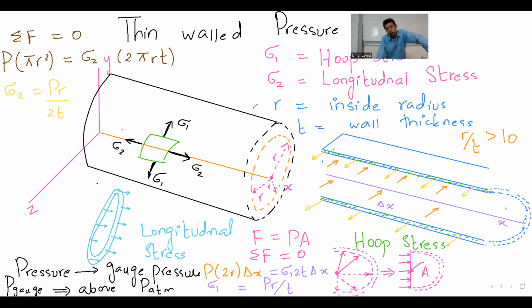Just one thing. Let's not use the word radial stresses for hoop stress. I think I was wrong, because when I make this cut, you see on this wall I have these yellow arrows in this direction. So I don't think we can use the word radial. Longitudinal is along the axis, and these yellow lines are 90° to it. Don't use the word tangential. It's just hoop stress.